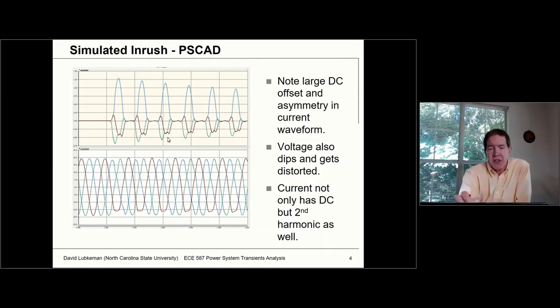And what we actually see in this case is when we have this inrush, one of the phases would tend to have a large inrush characteristic depending on the point of wave. And then you would see this in the other phases as well, not as bad, but you would nonetheless see this effect. And what this is going to do is cause deviations in the voltage.